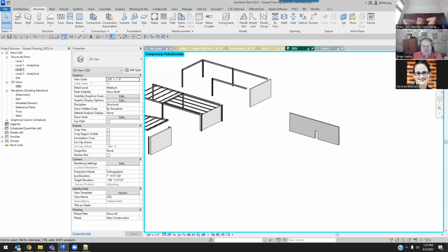Yeah, we actually added it to our ACAD.lsp, the list routine that opens up with every drawing to purge the reg apps. Wow, that's so interesting. It just automatically does it. Yeah, and then the audit in CAD is always a good suggestion, which I don't know, every time I do audit in CAD, it never finds anything wrong. It's like, okay, but.